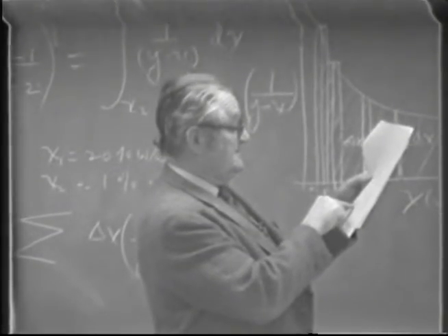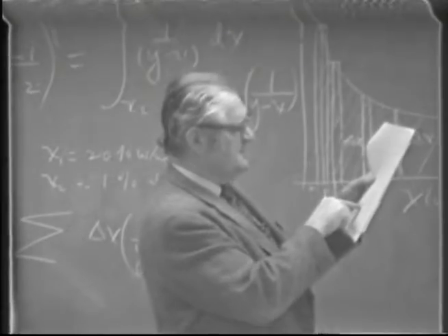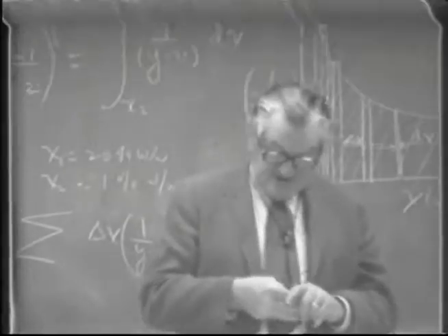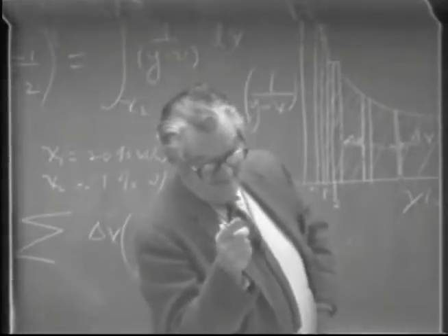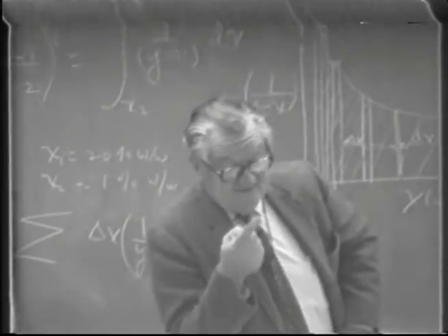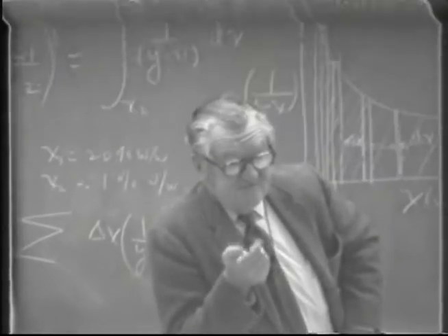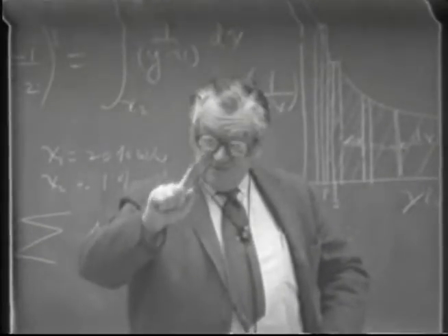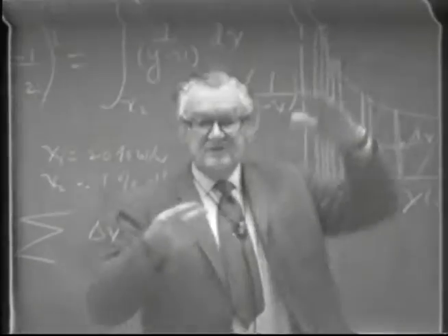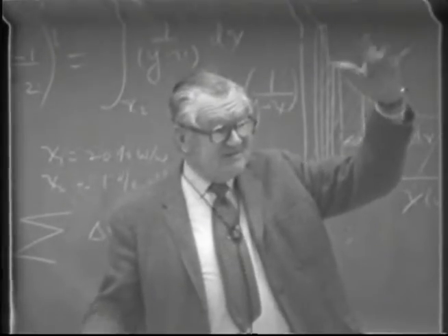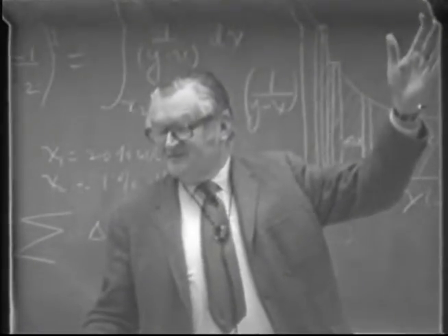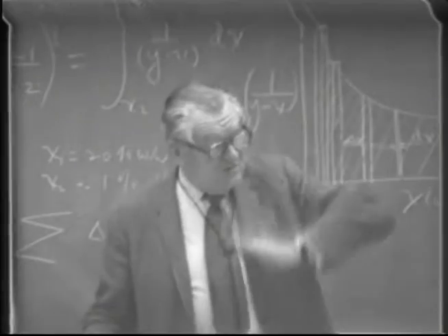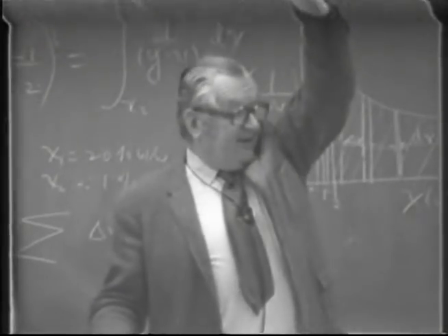Well, I guess this didn't illustrate too well, but it would naturally go up because of certain solubility. But in reality, the most important factor in this particular incident I just related was the fact that this high rate of water, then recycled back to the column, was diluting the column. So in effect, you had a section of the column that was acting like an extractive distillation column, causing the fusel oils to go up high in the column,